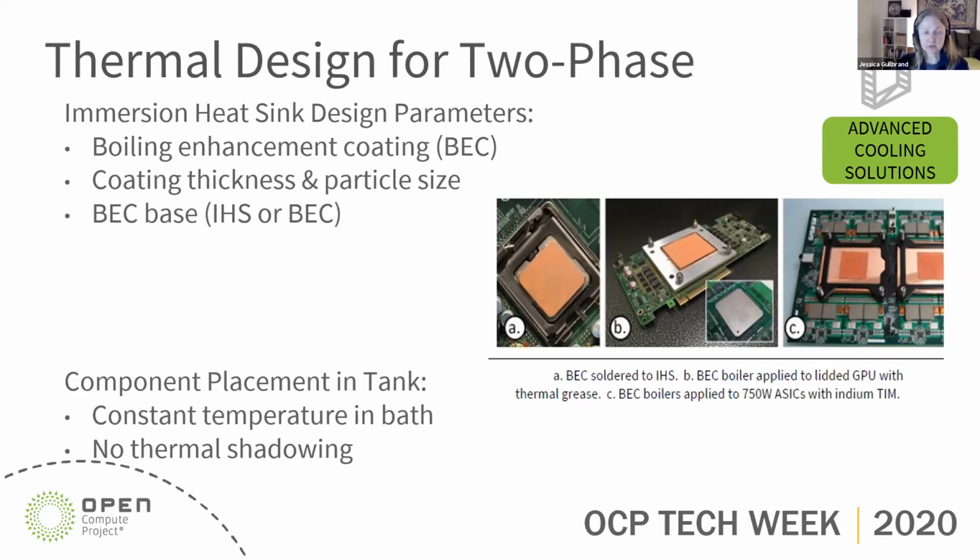When you're considering two-phase immersion and component placement in the tank, you're dealing with constant temperature in the tank because you're operating at the boiling temperature. And you're not really dealing with any thermal shadowing effects. Those are different design considerations than for single phase, so these are good to be aware of.